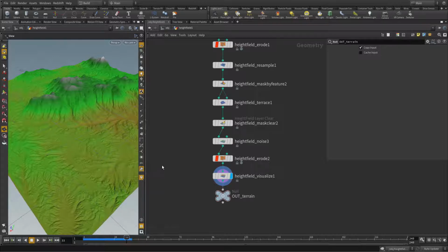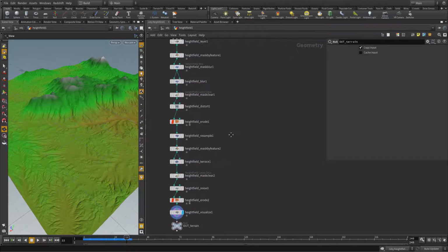And the good thing is that Houdini not only is able to procedurally generate geometry, but it can procedurally generate images. So with generating images from the volumes, we can feed the information directly live to Redshift without the need of baking out. Because of course you can bake out everything, but then you have to redo this every time you alter your terrain, and that is not very workable.